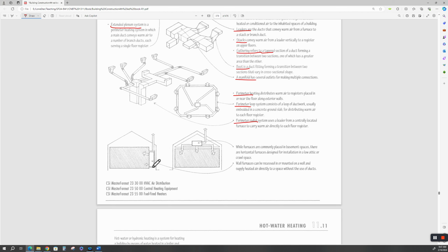Wall furnaces can be down wall furnaces in the wall, and the benefit of these, if you can do your architectural layout right, is you can bring in your makeup air from the outside, balance it, because remember, we still need to refresh the air in these structures, right? So he talks about that. Furnaces are in the attics, in basements, you can put them anywhere. But they do need makeup air, because what does it take to drive a flame? It takes fuel and oxygen, right?